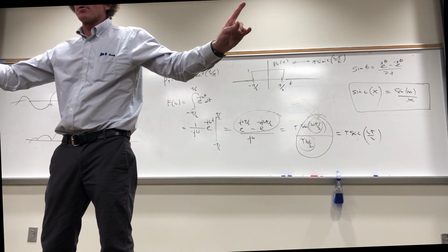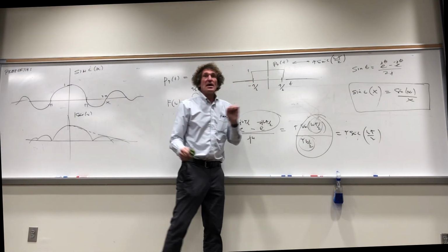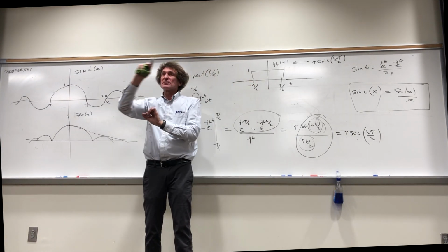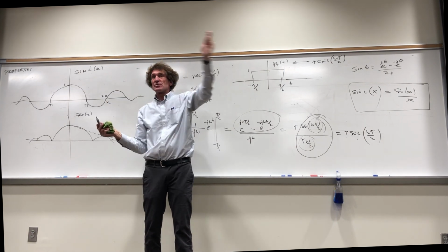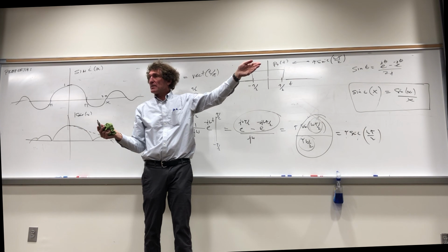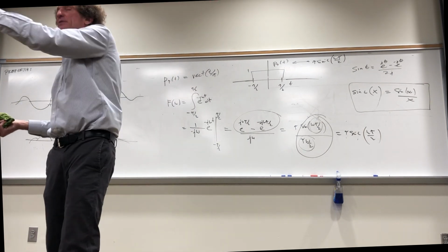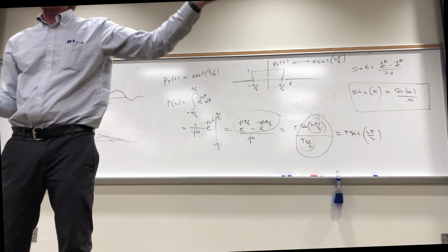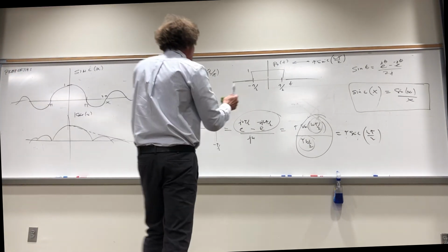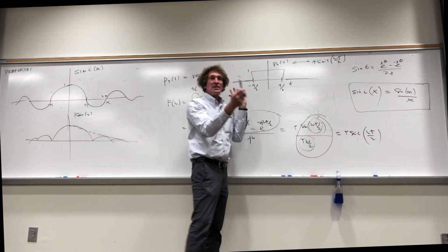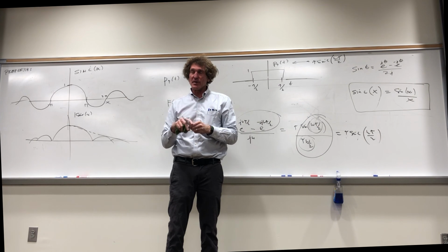This is real important. And in the limit, as this thing went to be an impulse, you would have just a constant value all through the frequency domain, same magnitude. Remember, a delta t goes to 1, right? What does that mean? It means the spectral energy or spectral signature has the same magnitude at every frequency. A delta function is extremely wide band. And the broader this thing gets, the closer to DC all the energy is. Remember that. That's a standard thing that you need to think about as engineers.